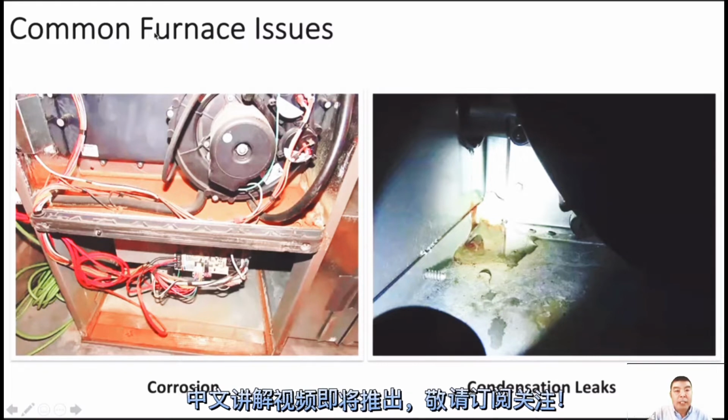So the condensate drain line may be clogged, and the water runs through the inside of the furnace to the bottom. So if there's rust on a category 1, you should check if there's a coil there, and maybe it's clogged.